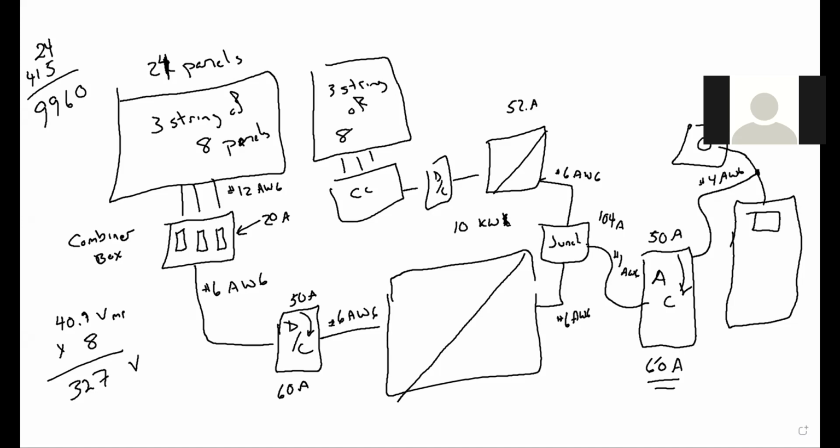Well, this 60 amp box, no longer any good. So we've got 104 amps. Well, that has our safety margin in it. We could probably get by with a 100 amp box, but let's assume not. So we'll probably get ourselves a 200 amp AC disconnect. If I put a fuse of some sort in here or a breaker, I'll go with like a 110 amp breaker or fuse in here. And now, of course, the wire that's leaving here is going to have to be at least 1 gauge, maybe bigger. And we will have to do a supply side connection.